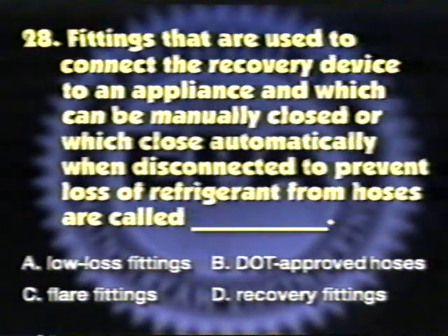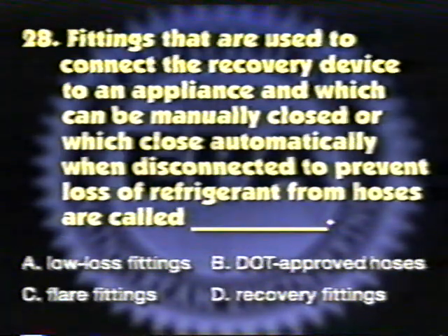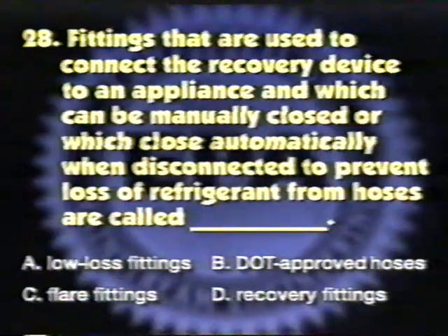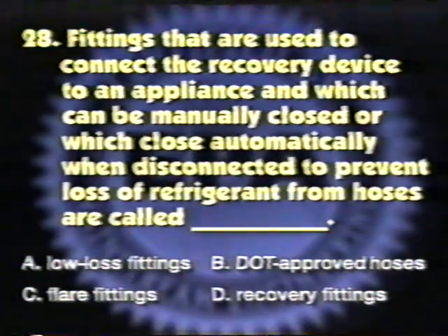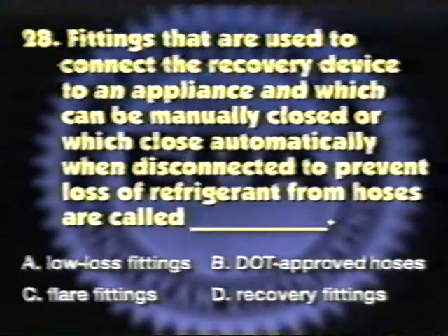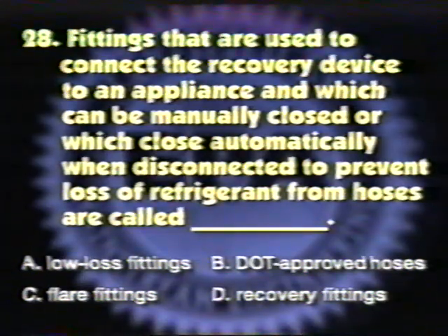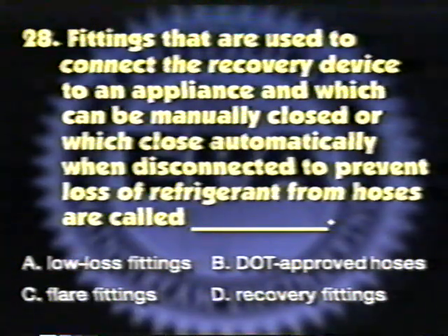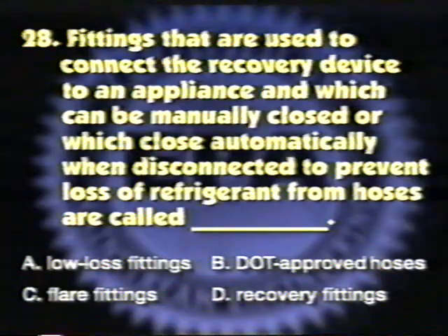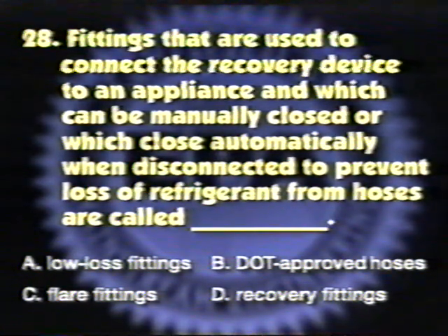Fittings that are used to connect the recovery device to an appliance and which can be manually closed or which close automatically when disconnected to prevent loss of refrigerant from hoses are called A. Low-loss fittings, B. DOT-approved hoses, C. Flare fittings, D. Recovery fittings.